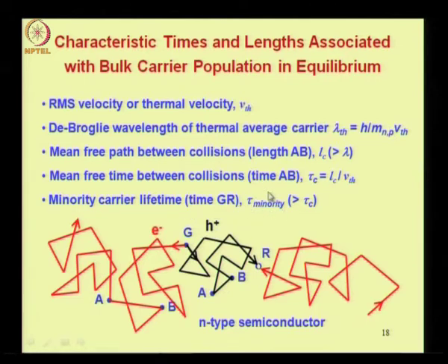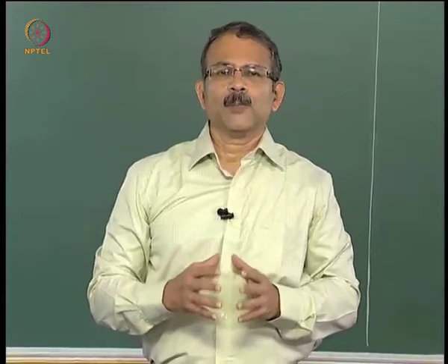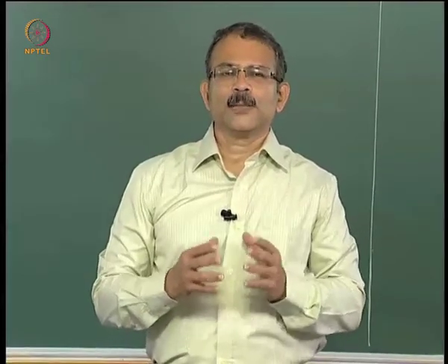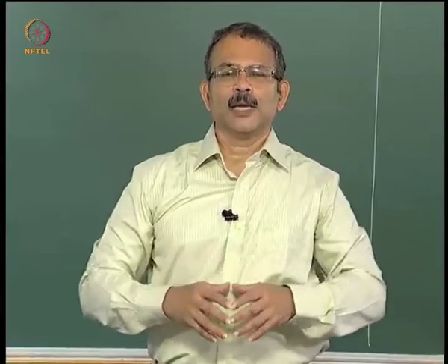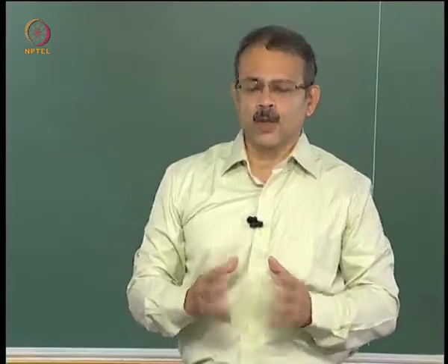Now, evidently this time will be more than the mean free time between collisions, because the carrier encounters several collisions, several scattering events, before it recombines after it is generated. Similarly, there is also a majority carrier lifetime. However, we normally do not discuss the majority carrier lifetime very much, because in device phenomena it is the minority carrier lifetime that plays a role.